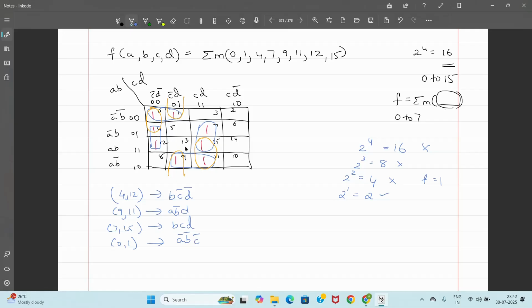They are prime implicants and a possible way of grouping, but not required here. I don't have to repeatedly cover ones which are already covered in some other group. If 0 didn't have any other option, then this would be needed and you could overlap. But here 0 and 1 can be separately paired, so I don't have to group them with something already covered.